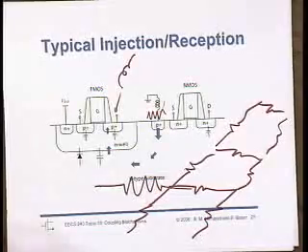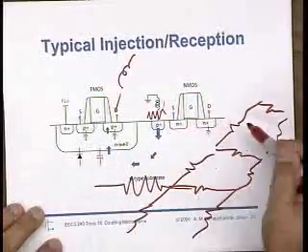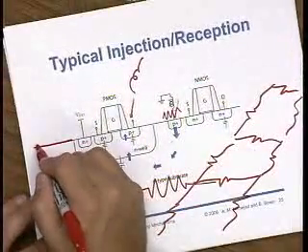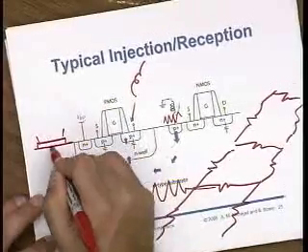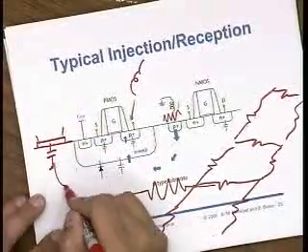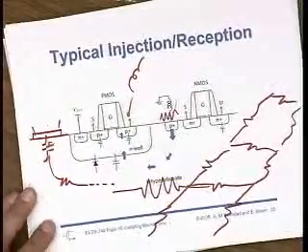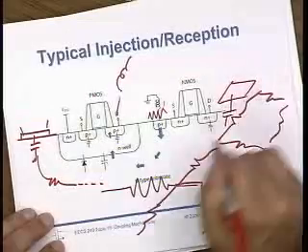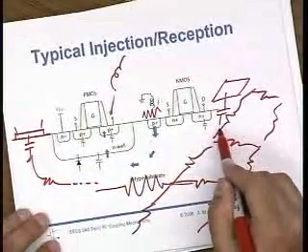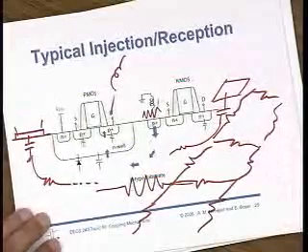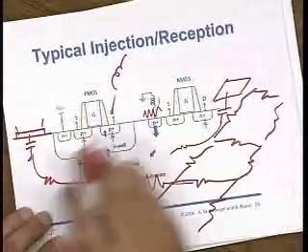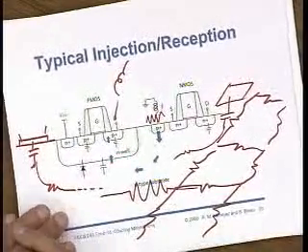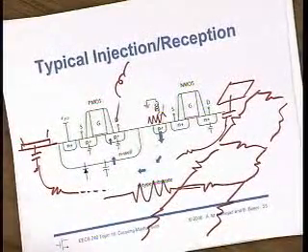And of course, don't limit yourself to just this path. Anything you put on the substrate has capacitance to substrate. If I put, let's say, a resistor, piece of polysilicon, well, that has capacitance to substrate. And that couples to the substrate. So my resistors couple. If I build a capacitor, right, it has bottom plate parasitics. Where do they go? They go to the substrate. So that couples to everything else. So not just transistors, but also passive devices easily couple to my substrate. Okay? Questions or comments?